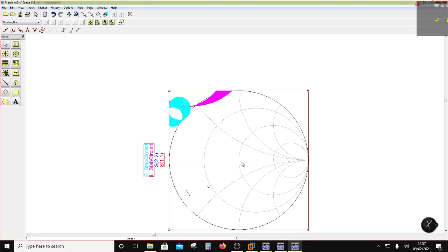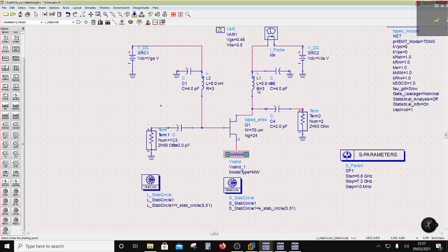So now you know, when I did the DC parameters, why did I terminate them to 50? Because I want 50 ohm as a stable point. If 50 ohm is a stable point, then my DC characteristics are correct. Usually what people do is they don't put decoupling here.